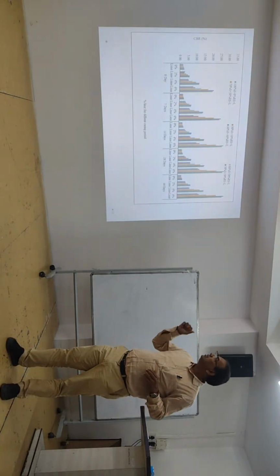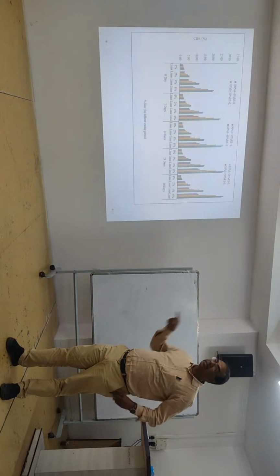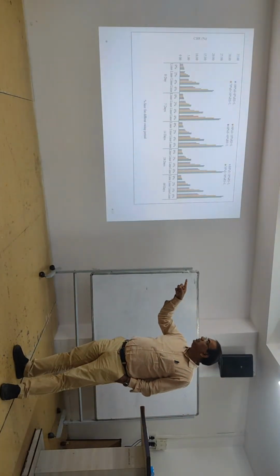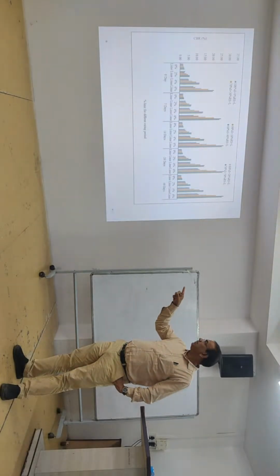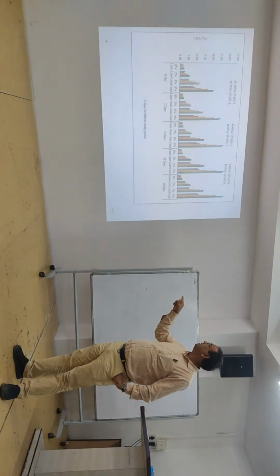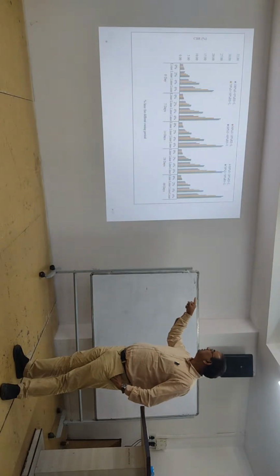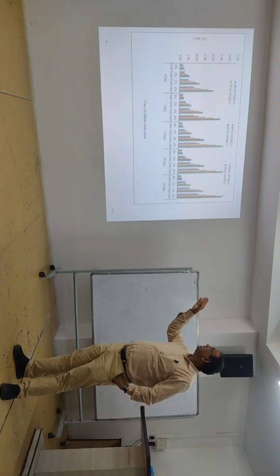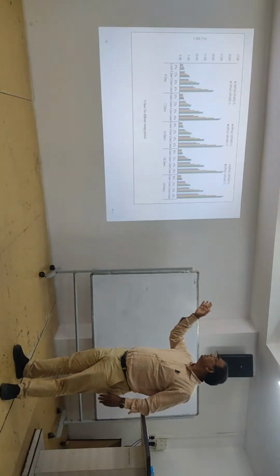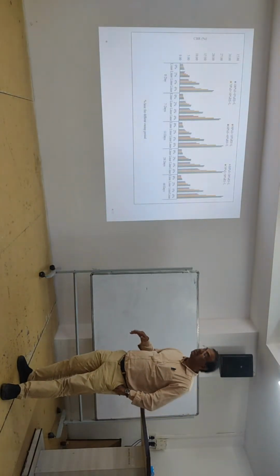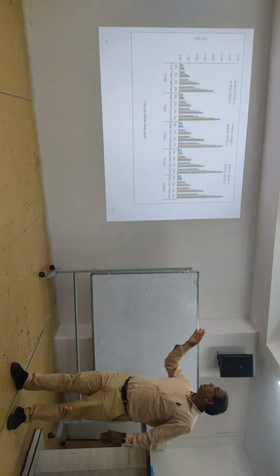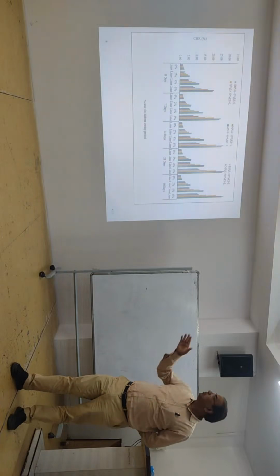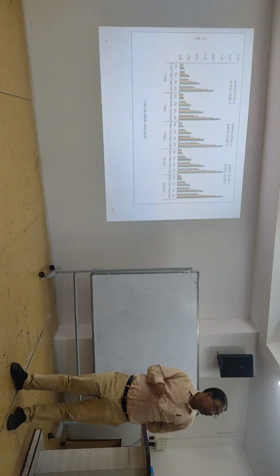You can see 0 days CBR value of this 100% soil. You can see that and different. So 0 day, 7 days, 14 days, 28 days, 60 days. And you can see that 6% lime with your 50% soil and 50% recycled sand. The strength is almost 30 CBR we are getting. Means strength from 2% to 30%.